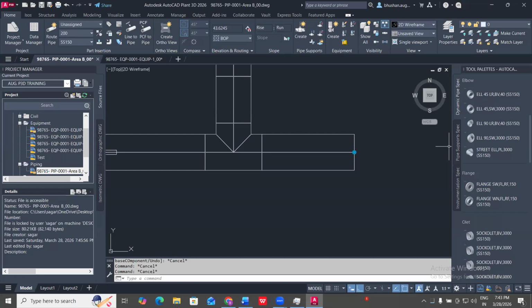Also, there is one more important note, which you can write down for understanding. If a custom elbow or pipe bend is not showing up in the substitution list, check the spec editor. The path angle of the custom part must exactly match the path angle of the part you are trying to replace.